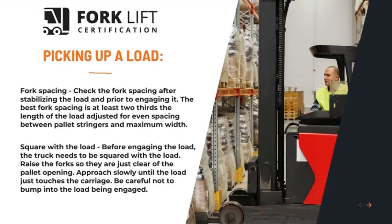Picking up a load. Fork spacing. Check the fork spacing after stabilizing the load and prior to engaging it. The best fork spacing is at least 2/3 the length of the load, adjusted for even spacing between pallet stringers and maximum width. Square with the load. Before engaging the load, the truck needs to be square with the load.